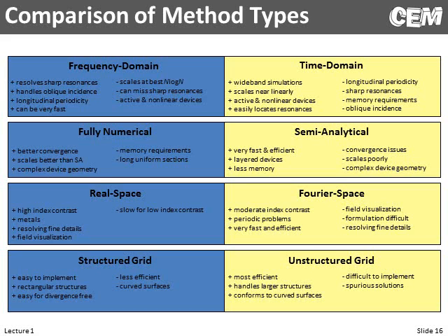Fully numerical versus semi-analytical. Fully numerical will take our governing differential equation that we want to solve, and we'll do whatever approximations we do, but we do it to everything, and then solve it as a big matrix equation. Semi-analytical will take usually 3 parameters, x, y, and z. We'll take x and y and do our numerical approximations, but the z will leave analytical. Now we actually sit down with pencil and paper, solve a differential equation, and plug that back in.